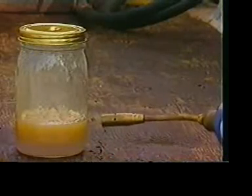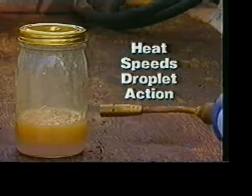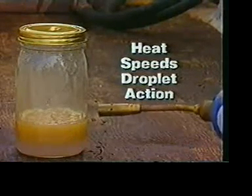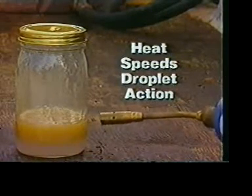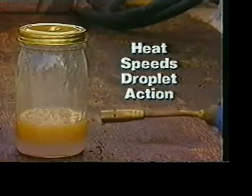Now, heat alone will not break an emulsion, but it aids in several ways. Heat causes the water droplets to move around faster, striking each other with greater frequency and force. As the droplets collide, the film of emulsifying agent ruptures and allows the water droplets to combine, forming larger, heavier droplets. These larger droplets yield to the force of gravity and settle out.